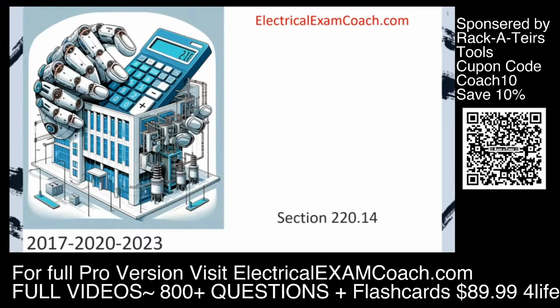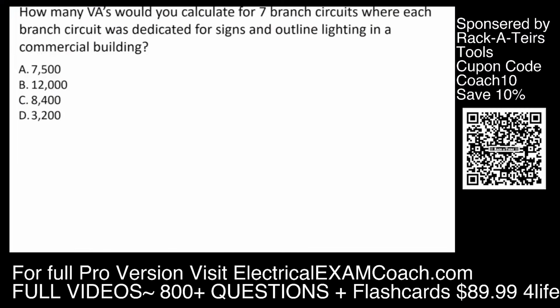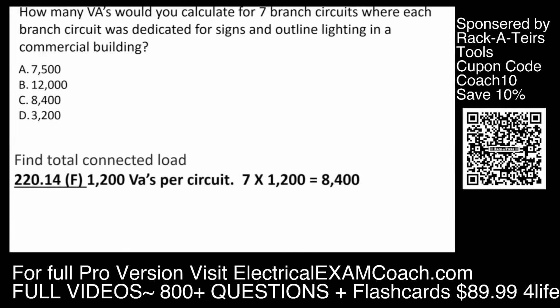Let's get to it. How many VAs would you calculate for 7 branch circuits where each branch circuit was dedicated for signs and outline lighting in a commercial building? Step 1, find our total connected load. For this, we're going to go to 220.14F, and it lets us know that for each circuit, it's going to be 1,200 VAs per circuit. We have 7 circuits multiplied by 1,200 equals 8,400 VAs.